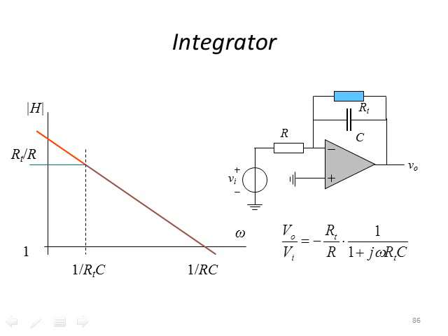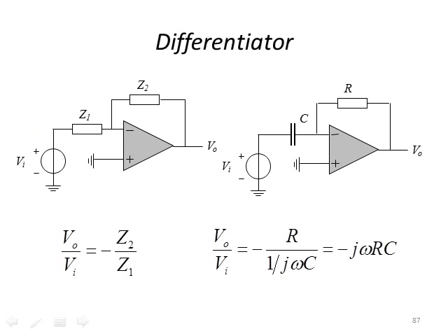And then the integrator again, with another resistor connected to it to be able to push the passband out and to be able to adjust the time constant, so you can extend the passband in the frequency domain.